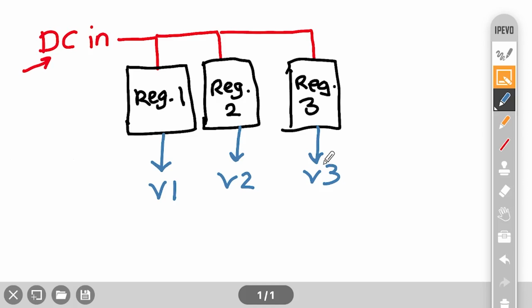Or you have dense groups of components, or you might be operating at very high currents in some areas. In these cases, it's usually best to have a power plane, and you can cut the plane up into sections to provide different voltages as needed.